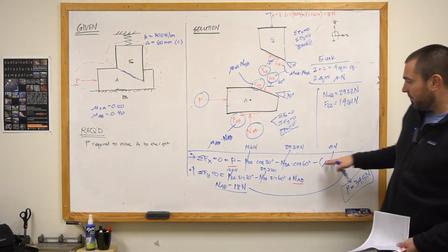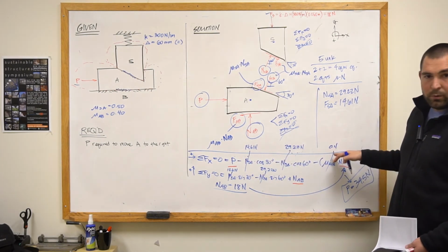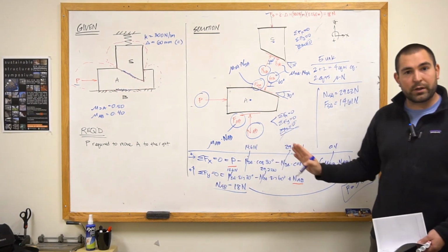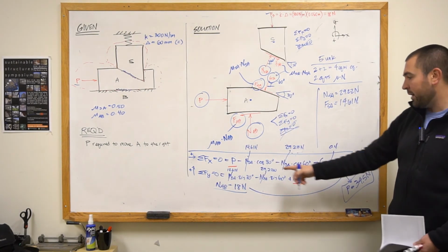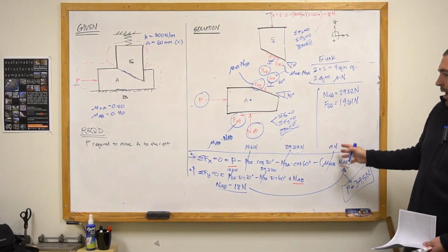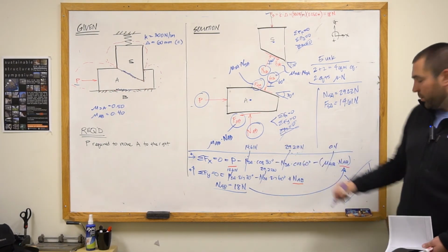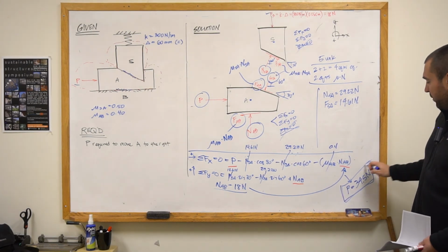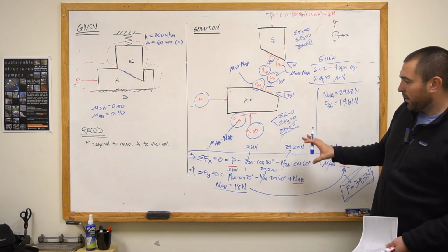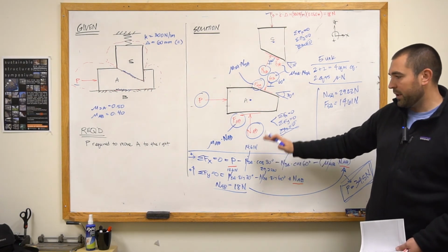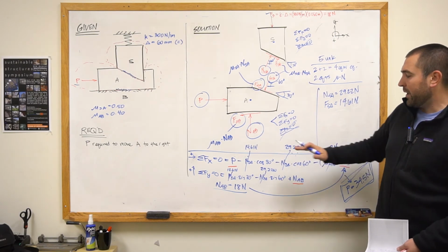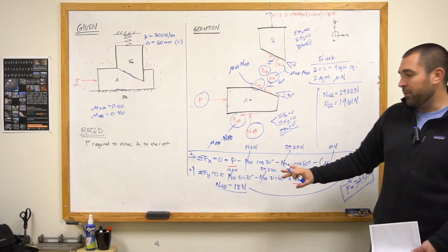All that I did is I left that equation unsolvable. I went to the next equilibrium equation, sum of the forces vertically. I solve for NAB, and then I just go back, I plug it into my original equation, and now I only have one unknown, which would then allow me to solve for P. So again, I know a lot of students get kind of frozen and they say, well, I don't know if I should sum the forces in the x or in the y or do moments if that's available as well too. It doesn't matter. It won't give you the wrong answer.